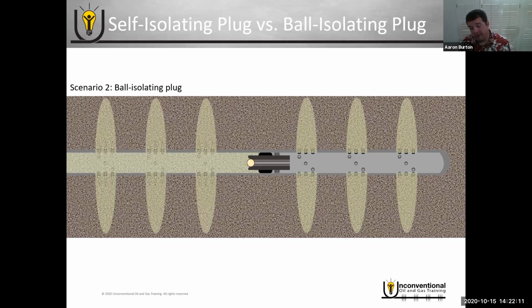Now, over the years, the perforation guns have really improved on the technology, so it doesn't happen as commonly anymore that the perforation guns don't fire at all. And also, because we have so many perforation clusters in the wellbore, like I mentioned earlier, 6 to 12, in a lot of cases you should be able to get 1, maybe 2 perforation clusters to fire. So that gives you the ability to pump in the wellbore.